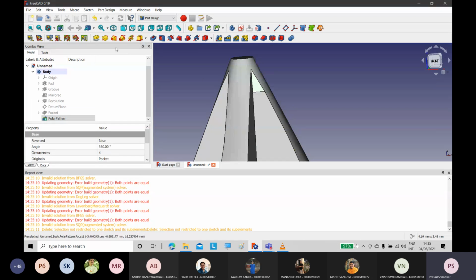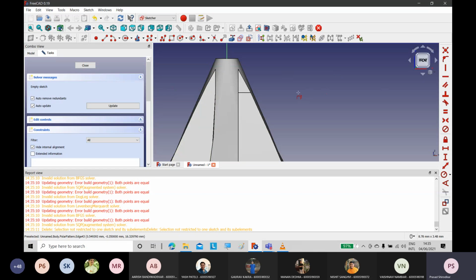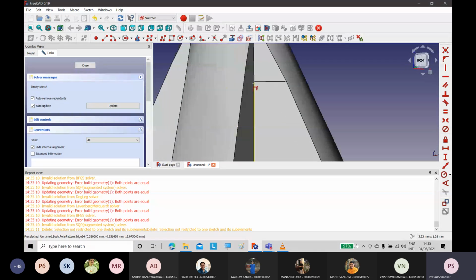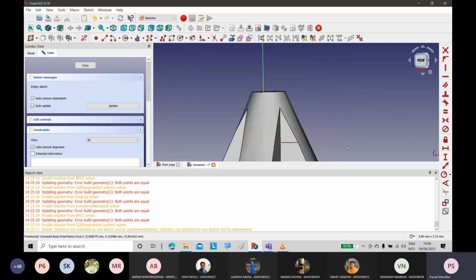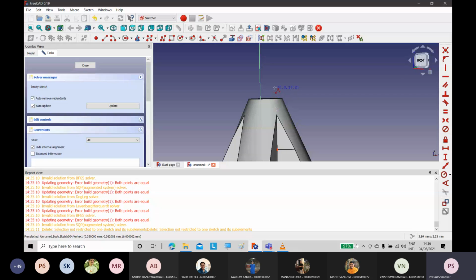Do it again. Here sketch plane, import constraint. Okay, dot. Then create the polyline by selecting the polyline option and make sure that you start it close to this vertical point and you join with this point, and it should be a vertical constraint.